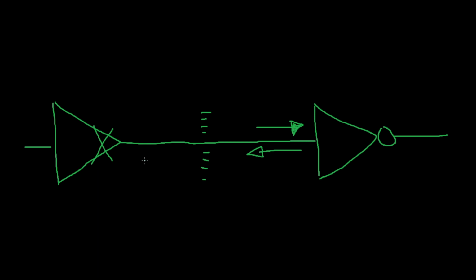If you were to connect a probe to this, then your probe is going to have some capacitance and some resistance going to ground, and that will eliminate the floating node and cause it to appear to be grounded out. It's very easy to look at a floating node and see nothing there and wonder, why is my circuit acting so strange? But as soon as you disconnect this, it goes right back to acting strange again.